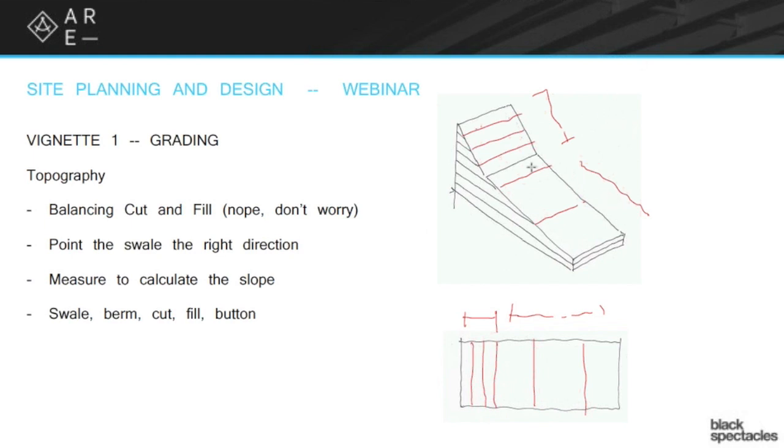So when you're thinking about this and you're trying to figure out how far apart these things should be in terms of those numbers that I was just talking about, while you're working on the program, you can use circles. Let's say we're trying to make sure that something is not steeper than 20% slope. So if I use a circle that represents 20 over 100, which would be 1 over 5, I use a 5-foot circle.